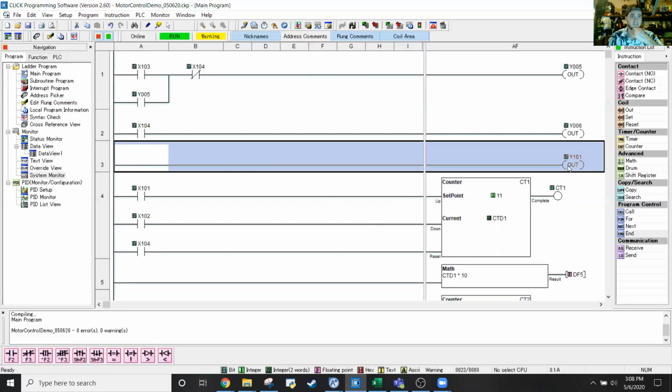Generally speaking, this is something you do not want to do in PLC programming. Because it means anytime the PLC is in run mode, that output is energized, no matter what. And you have no way of programmably or physically interrupting that, short of pulling a wire.